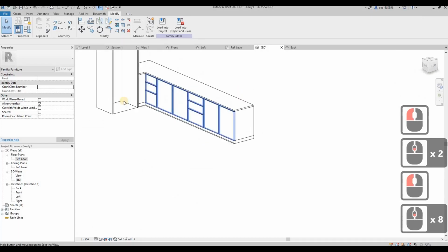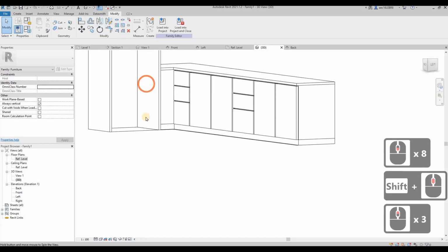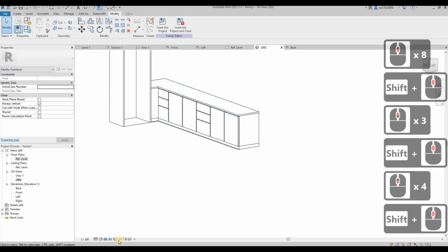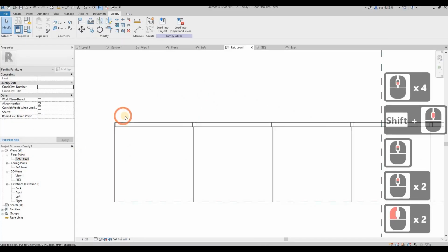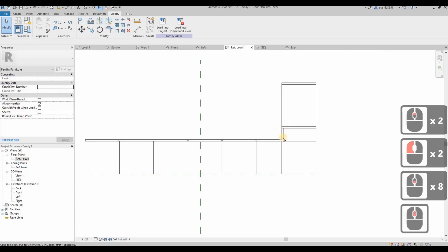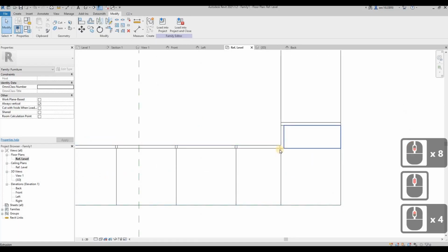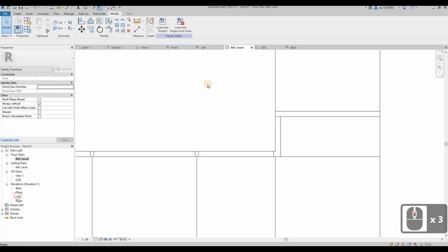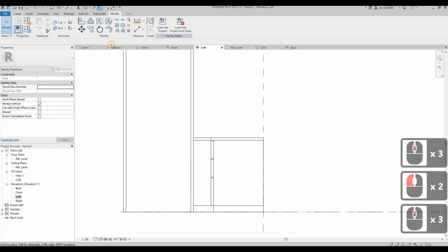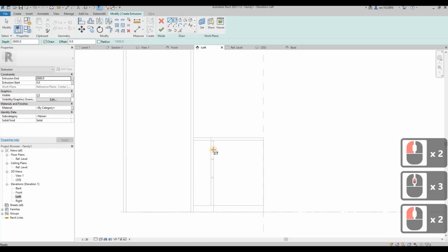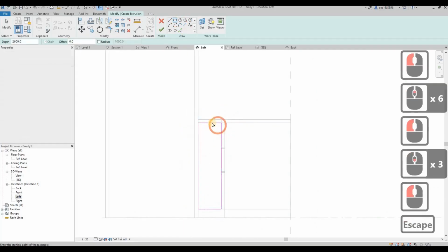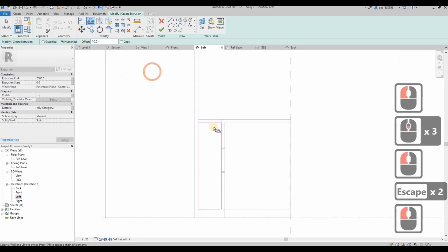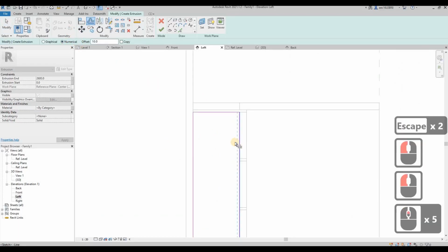So this is your cabinet with the drawer, and then for this side we go to reference level again. From the left view, you can start to model this part of your cabinet. Let's create extrusion to cover this place. Offset it to 10 mm here.